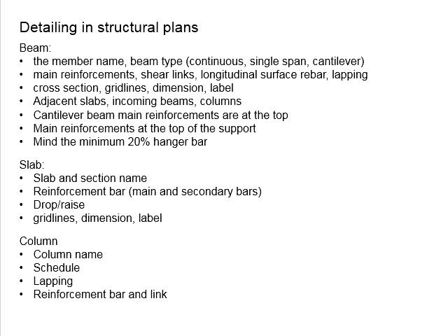Be careful with the incoming beams. You need to correctly indicate the size of the incoming beams. It is so that you can imagine the relationship between the beams at their joint, to know which one is likely to be the primary beam and which one is more likely to be the secondary beam. It also gives you information to see the incoming beams attached to your beam member, giving you an idea in terms of the structural integrity between the joints.